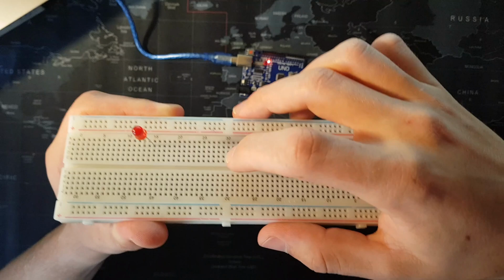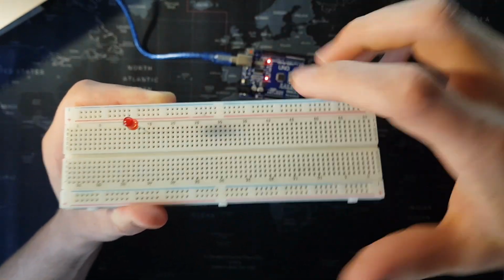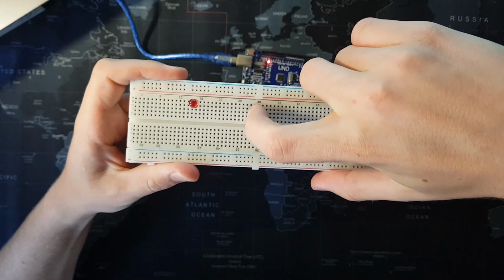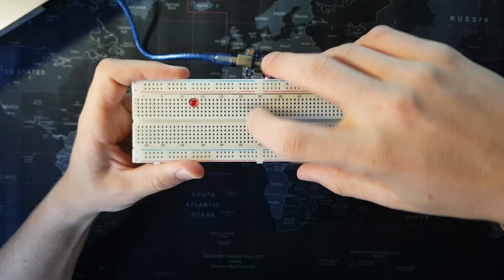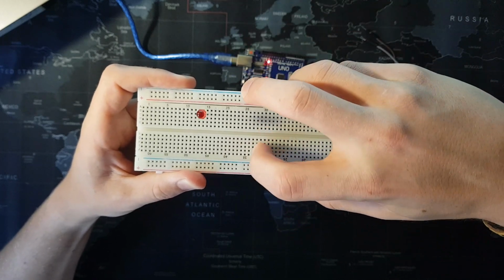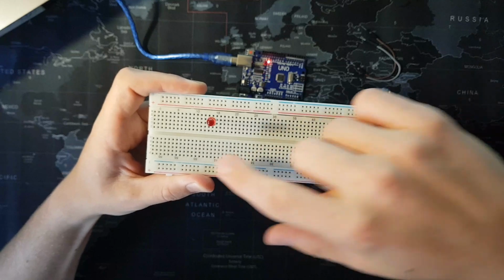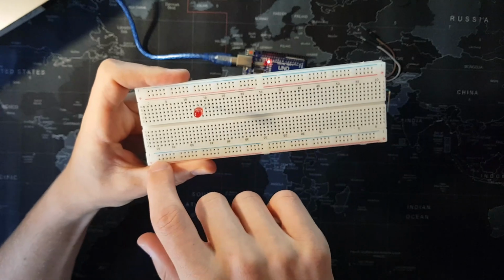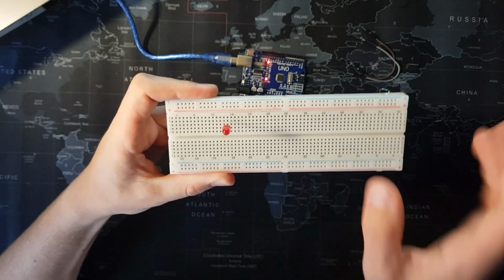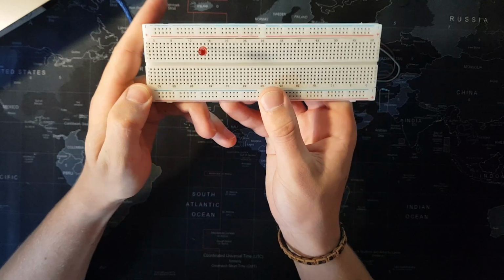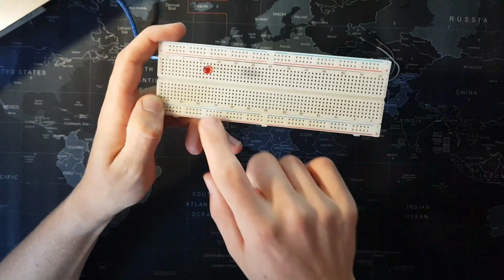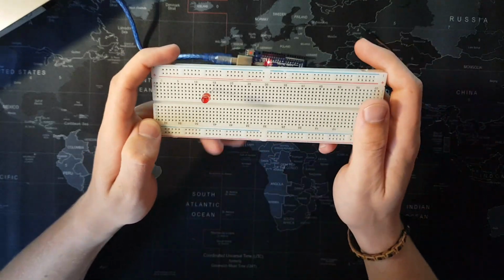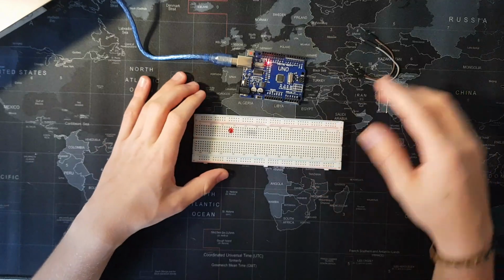With the breadboard, we've got rows that run along from our orientation here vertically, and each row here is connected, and there's a disconnect between these two sides, and then it's the same there, and it runs like that down the breadboard. Then these over here, these long ones, are called power rails, and these run horizontally, and these are all connected up. If you want both of these rails to be powered up, you just need to put a jumper cable between the two. But yeah, that's just the basics of the breadboard.